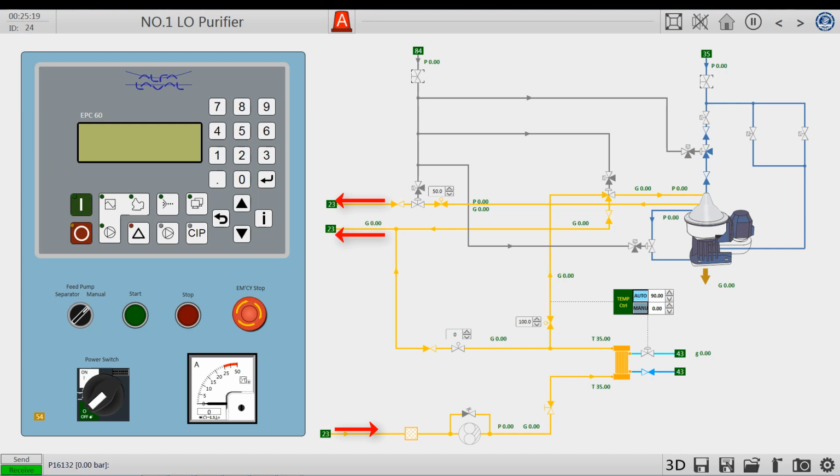Except for the three external oil lines, there are also a control air line and a fresh water line. The control air line is used to control the start and stop of each relevant pneumatic valve, and then control the oil and water pipelines on/off. Fresh water lines supply fresh water for the oil separator.